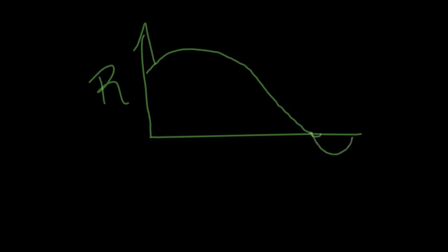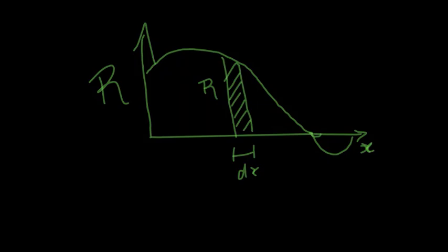The way you make the residual area 0 is, if you want to find the area beneath this error curve, the height of this strip is going to be r and the length is dx, because r is being plotted along the y-axis and x along the x-axis. The area of the small strip is r into dx. Now how do you find the total area? Well, you have to integrate it over the limit 0 to L.